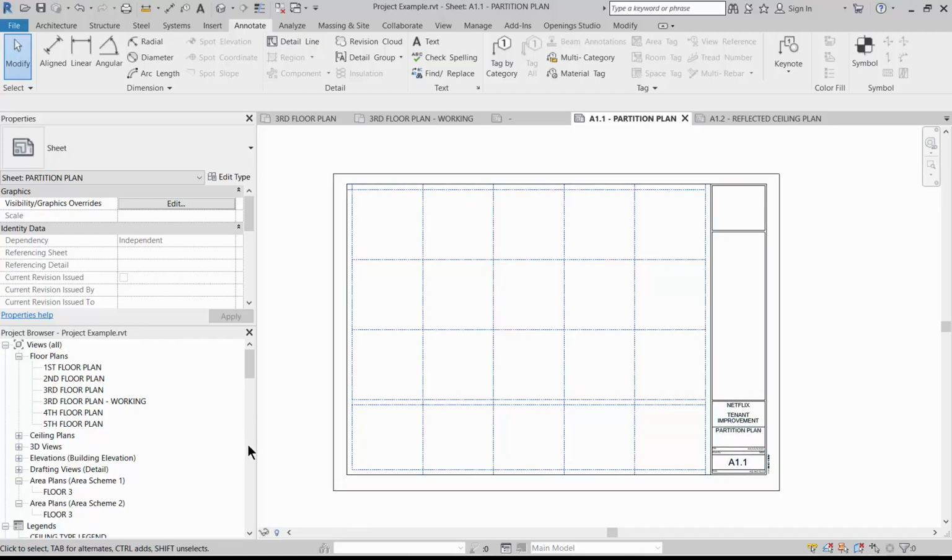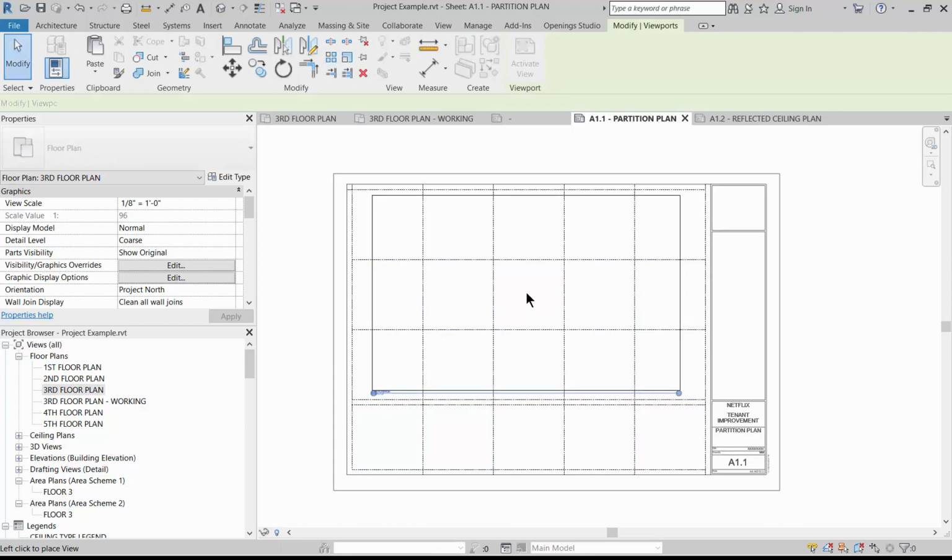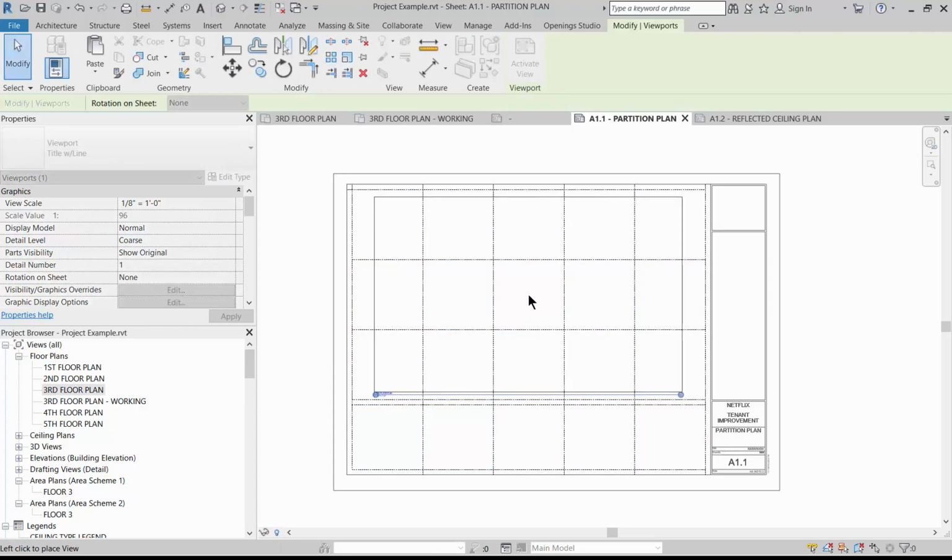Now that our basic subdivision of the sheet is done, the next step is looking at the titles of all of the individual views. So first step, let's place an actual floor plan view on the sheet. You do this by just dragging them from the project browser. And as you can see, my particular view will necessitate that my border be on the bottom because the view itself is too big to be placed off to the left hand side, and in order to use the vertical tile.